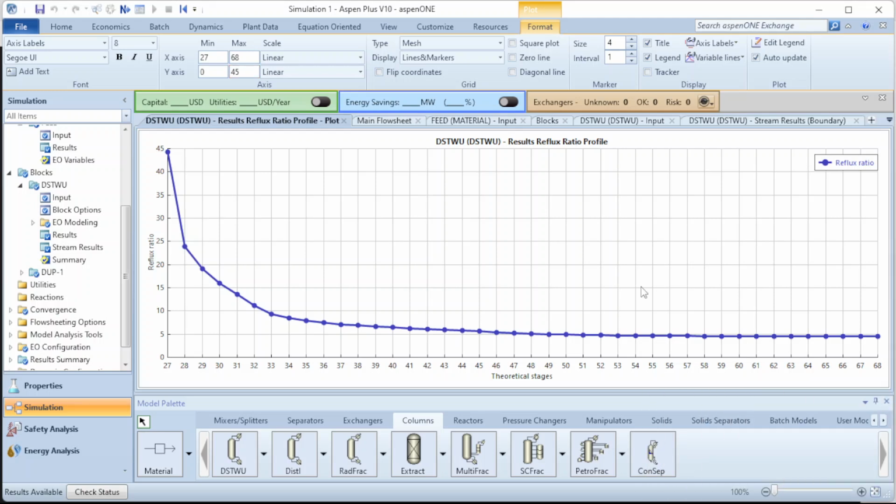So a caution for the people that will be designing their plant: if you just increase the number of stages maybe to 105 stages, your diameter will be something like, maybe 0.5. So that will be a tall column, and it will be like a cane, and just a little environmental interference, something like air being blown, and your column will just fall down. So let us take good care of this.